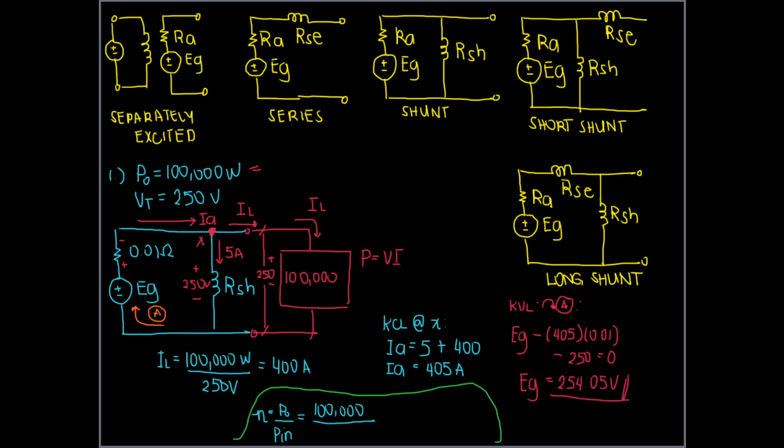So the input we are supposed to consider is not the mechanical power, rather it's the generated power. From the generated power, you will have electrical losses this time, before it becomes your final output. So the input we can consider is the generated power.